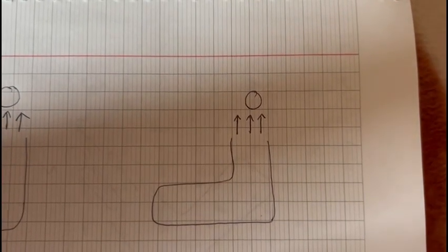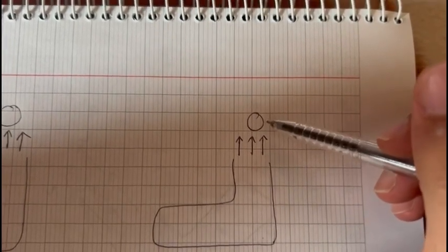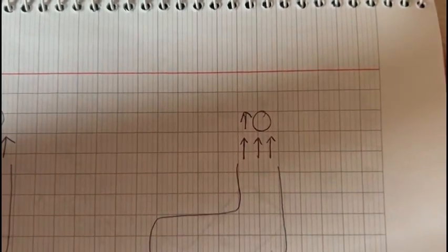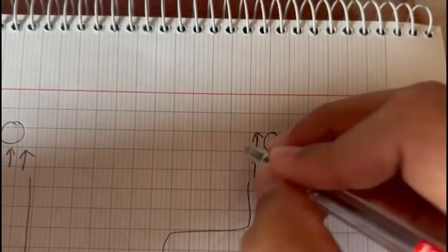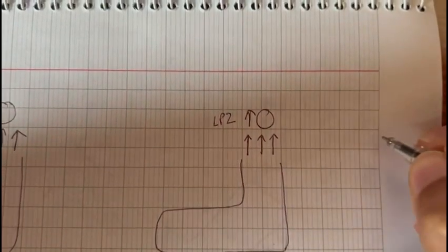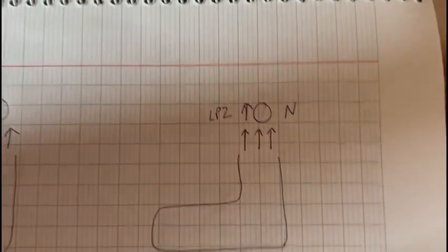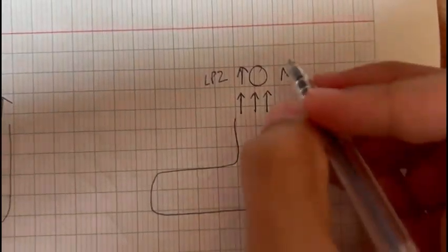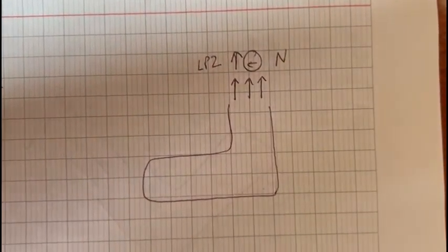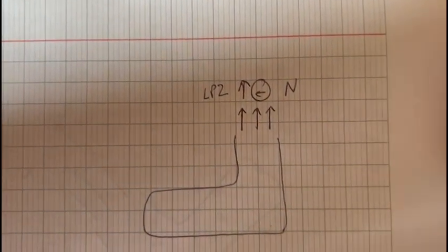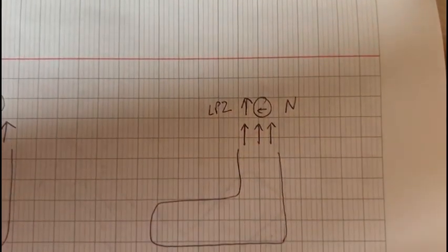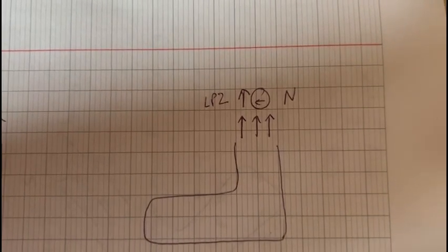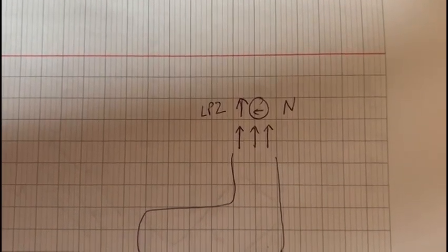So we can observe that when the ball does move to one side of the airflow, there would be more air passing by its side, creating the low pressure zone right here. And on the free end we have normal pressure, or relatively higher pressure. This pressure difference pushes the ball back into the airstream, not allowing it to fall off. This could happen on either side. The side that is free would be normal pressure, and air passing through would create a low pressure zone, with the pressure difference pushing the ball left and right.